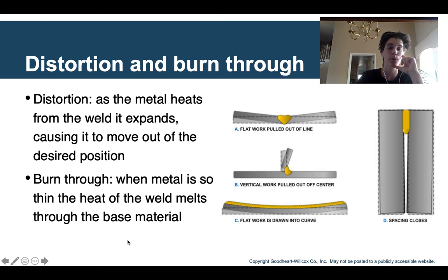And then burn through, we talked a little bit about penetration versus burn through. We don't want that look of burn through, what's sometimes called sugaring in TIG welding. We don't really quite get that same effect, but we don't want burn through, we do want penetration.